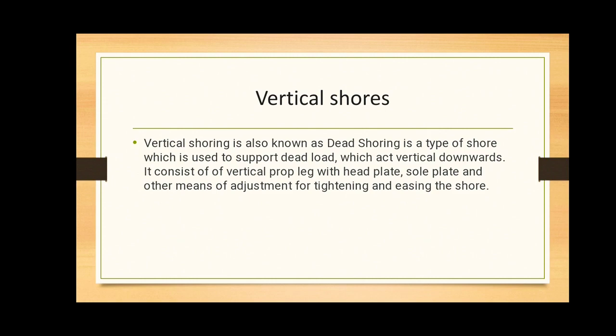Wooden needles consisting of thin sections are used to transfer the load from the walls, and they are first inserted into small wall openings, which are made just sufficient for the size. Horizontal beams are laid along the floors to support the dead shores, and the load is evenly distributed on the base. The dead shores are introduced and wedged tightly in between the beams and the needles.